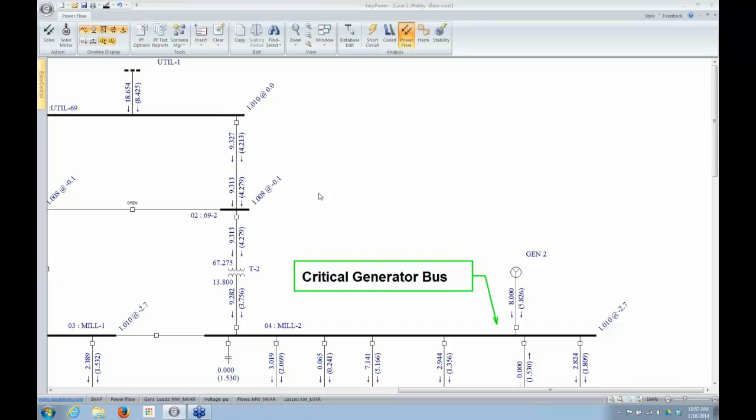Adjustable frequency drives and nonlinear loads create problems for the capacitors unless they're filtered. You may want to switch the capacitors with the motors and that kind of thing. So in an industrial facility, the location of the caps is more driven by practicality and technical issues rather than economics. The economics are to reduce the power factor penalty, and that is really just making sure it's on your side of the meter.